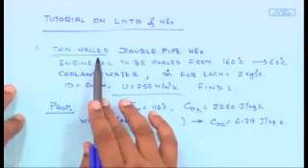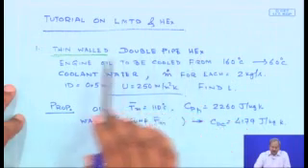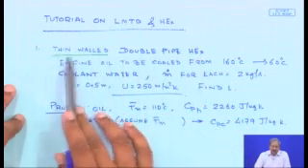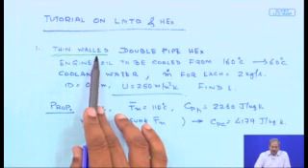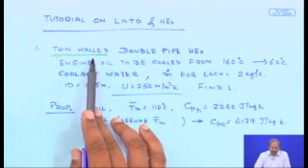So with that background, I think we are in a position right now to solve some specific problems in this class, and then from next class we will go into purely shell and tube heat exchangers, their efficiency calculation and so on. But right now let's concentrate on the first problem, which is a double pipe heat exchanger. It's a thin walled double pipe heat exchanger. I have underlined the words thin walled, so as to mean that essentially the resistance to heat transfer by the wall of the pipe is negligible as compared to that of the inside convection coefficient